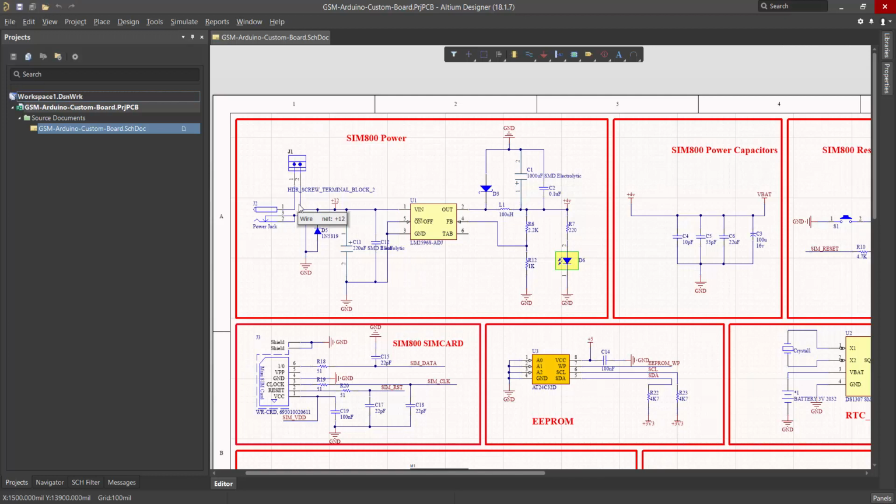For example, if the user mistakenly puts the positive of the power supply here and the negative here, this diode will turn on and short circuit, so the current will flow from here to here and go back to your power supply, so your power section and your board will be safe.